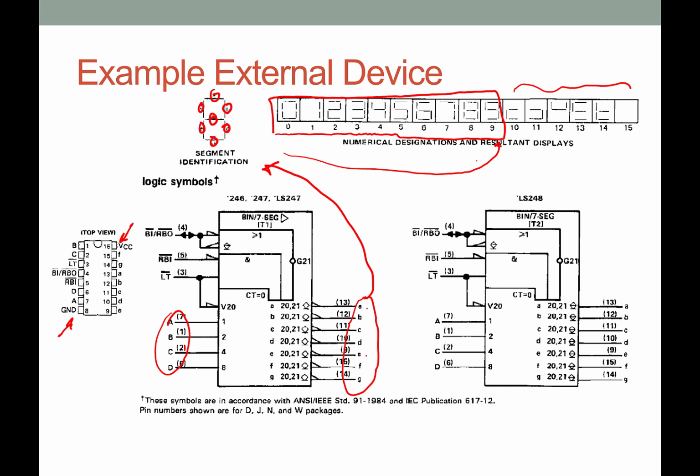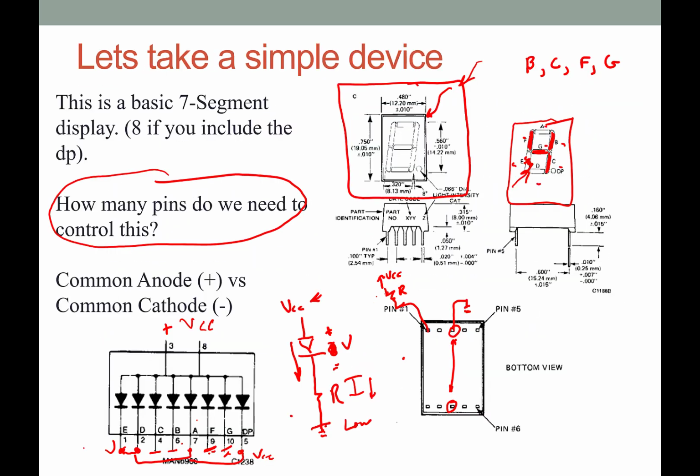The one thing you can see here is this is negative active logic, so that common cathode setup is what would be nice to use right here, because when it's a 0, that means it's going to turn on A, and that's what we talked about right here.